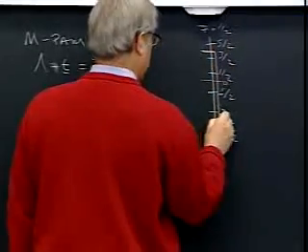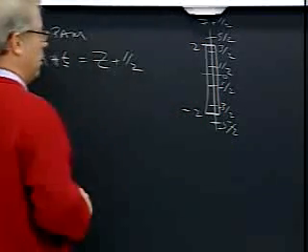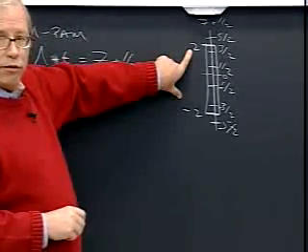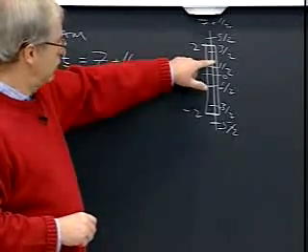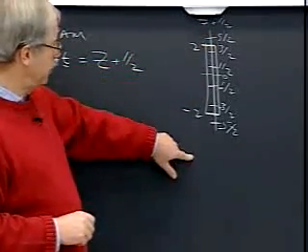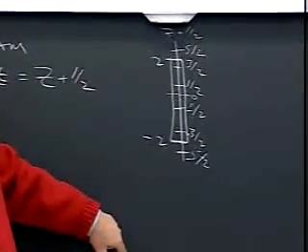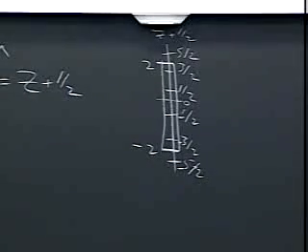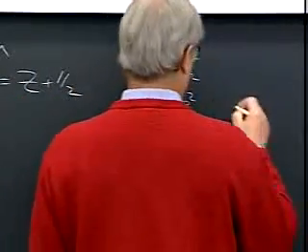And then if we want 4-PAM, we take a cookie cutter consisting of this region, going from -2 to 2. It's not unreasonable to expect that if we take a region of length 4, we're going to get 4 points, if it's symmetric around the origin, because each of these points takes up about 1 unit of space. So if we made it from -4 to +4, we'd have a region of length 8, and we'd get 8 points, and so forth. So that's how we do MPAM, and then scale it if we want to, but this is the basic idea.